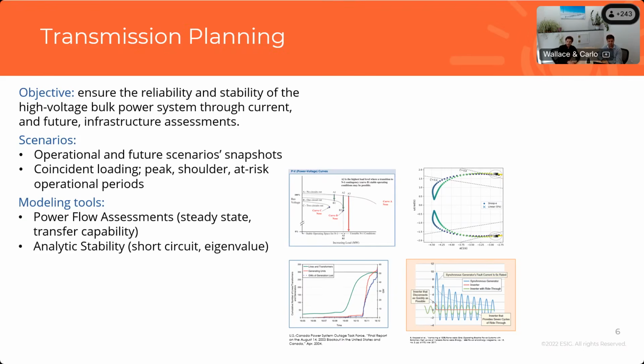But in the top, we have a classic eigenvalue trajectory analysis. Now, what we're doing here, which is also referred to as small signal stability, is trying to understand if the controllers and the assets on our system are going to be stable if I dispatch them in a particular way. So this allows me to look at all of the controllers and, without the presence of a contingency, understand if that system is stable in that particular operating condition.